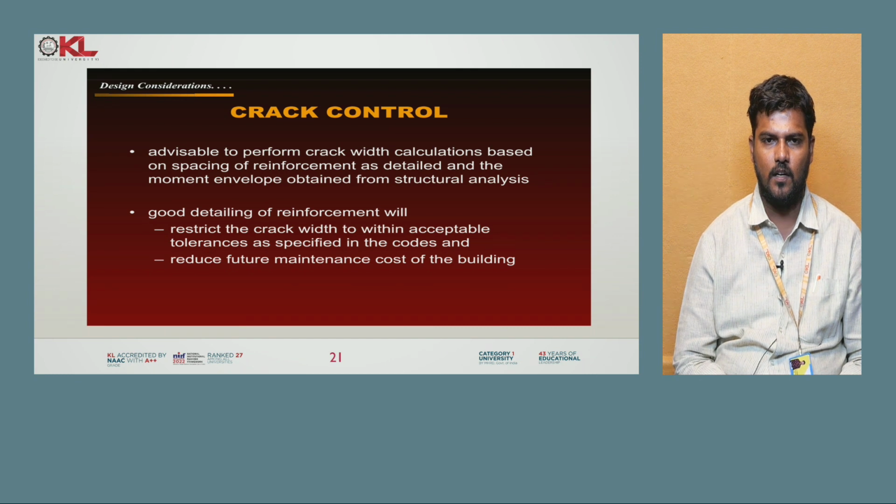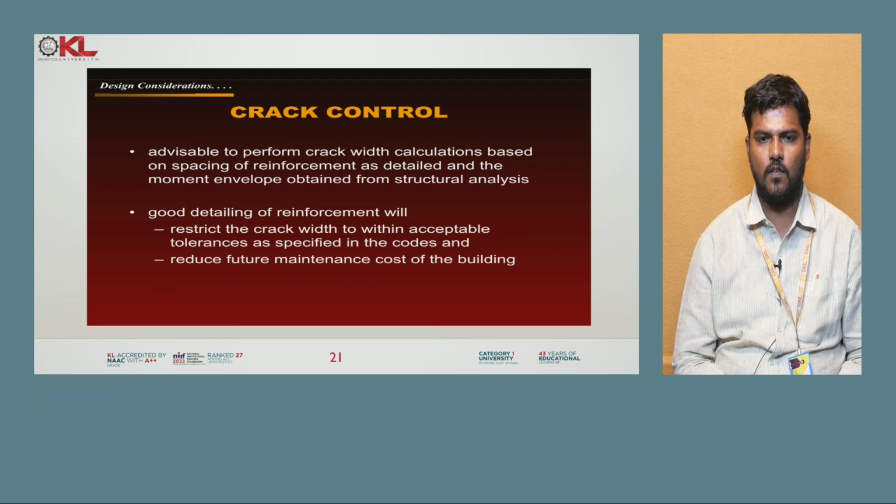Next one is about crack control. It is advisable to perform crack width calculations based on the spacing of reinforcement as detailed and the moment envelope obtained from the structural analysis. Good detailing of the reinforcement will restrict the crack width to within acceptable tolerances as specified in the codes, and it will reduce the future maintenance cost of the building.